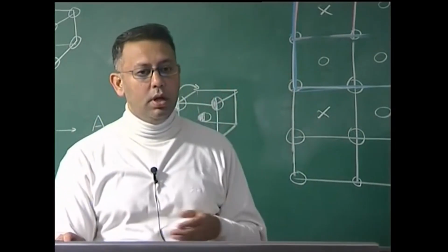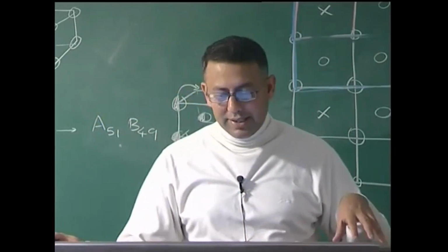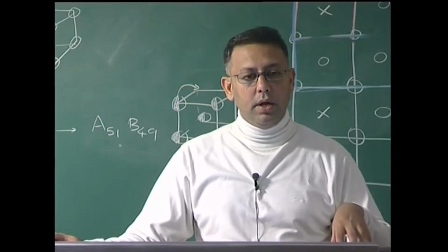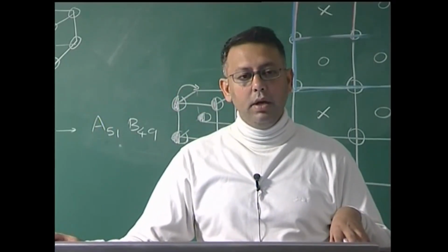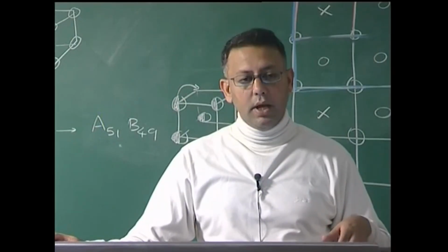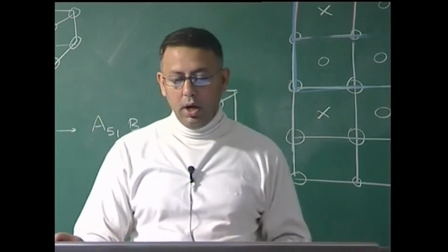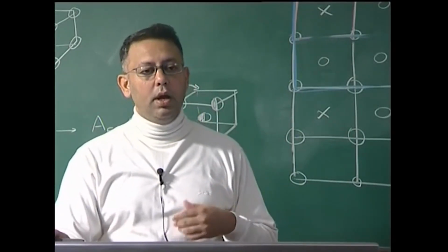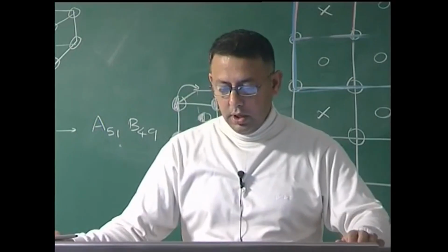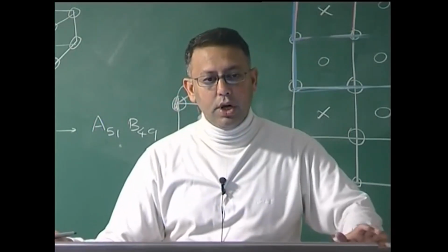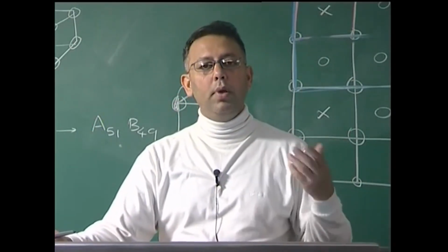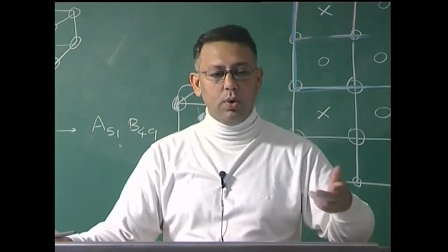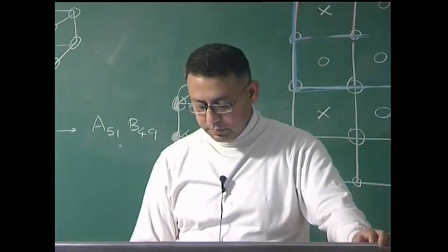The important thing is that within a single grain, which is a single crystal based on crystal structure, the single crystal could be divided into multiple domains, and the reason for doing so is a lowering of energy of the material, which otherwise in a single crystal would lead to high magnetostatic energy. So, domain walls, in spite of having high energy, are tolerated in materials in order to reduce the overall energy of the system, which involves magnetostatic energy, which throws out external magnetic fields.